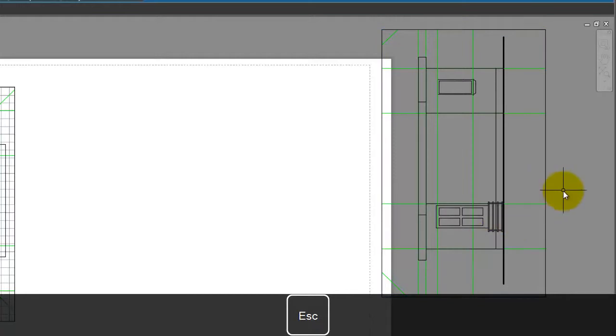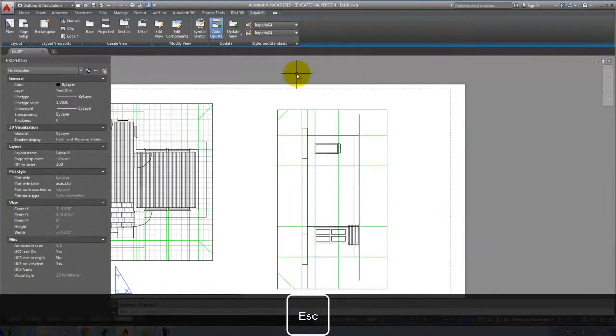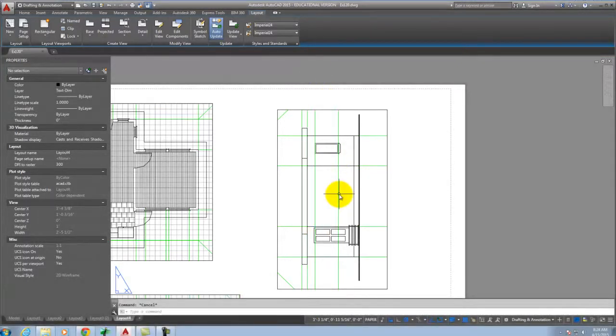Okay, so I drew this in a conventional manner. I'm just putting it over here so you can see it. But it's oriented 90 degrees from the direction I want it to be. Okay? So it's okay, but I would really rather have it oriented correctly. So what I want to do is make a transformation inside this viewport in that I want the viewport to display rotated.